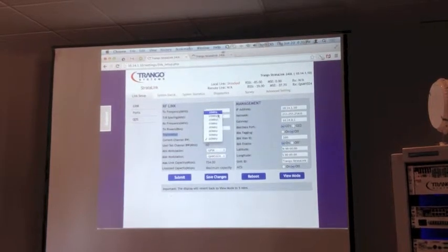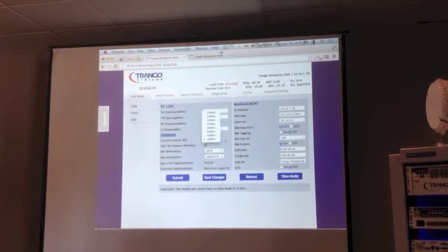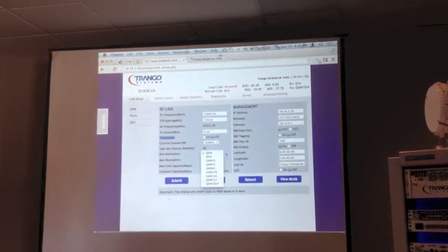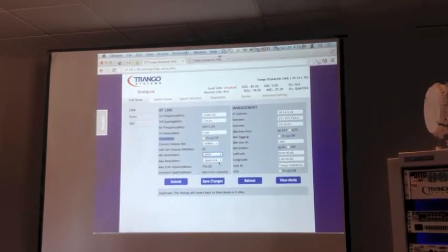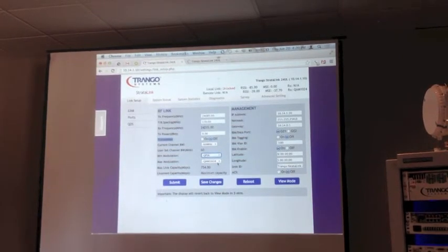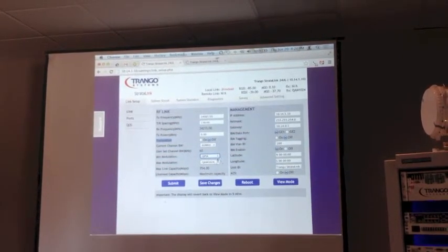Okay, you set your bandwidth here. So you pick what bandwidth you want it to be. Like I mentioned before, you set the min and the maximum modulation now. Okay, so there is no ACM on-off. ACM is effectively always on, but if you wanted basically ACM off, you could just set min and max to both be the same modulation.